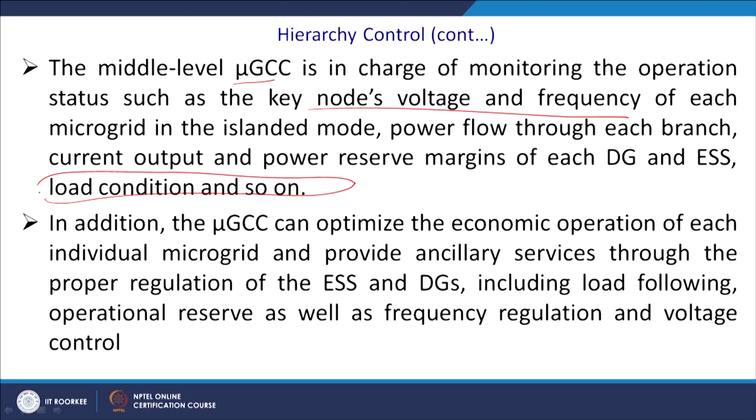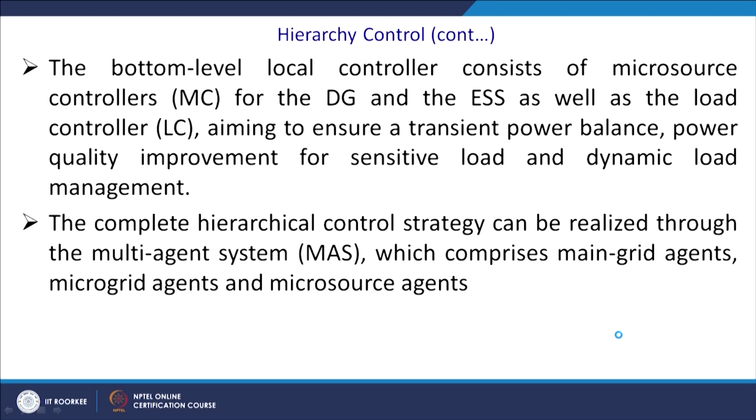This has been done by the middle level. In addition, this kind of microgrid can optimize the economic operation of each individual microgrid and provide ancillary service through the proper regulation of the ESS and DGs, including the load flow, operational reserve, as well as the frequency regulation and the voltage control.